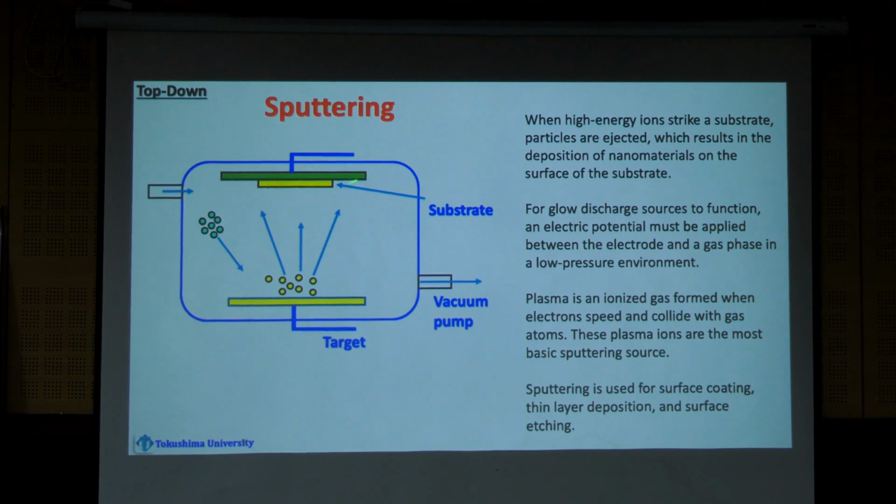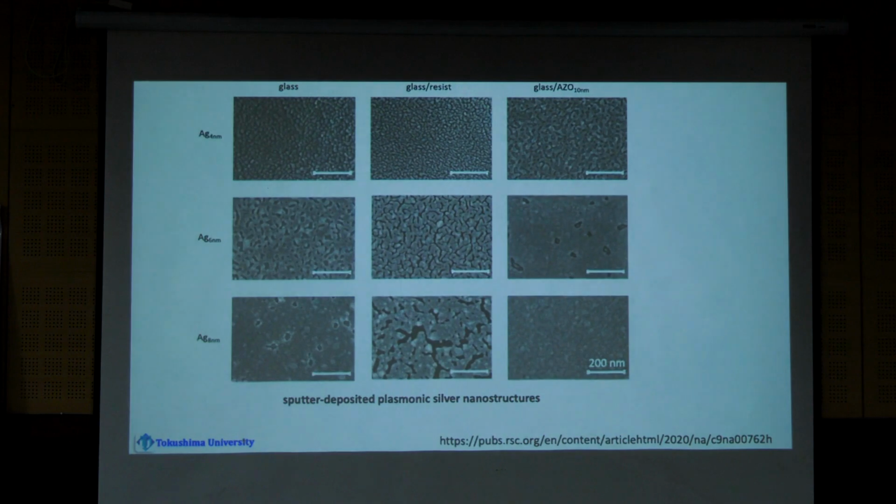Sputtering can give you uniform deposition. Also, sputtering is used for low nanometer scale. Like if you want a 1 nanometer coating, then sputtering is very good. A 2 nanometer coating of certain material, Ag, Au, you can use sputtering, and uniform deposition. Look at this, okay? These are examples like Ag, okay? 1 nanometer, okay? 6 nanometer, 8 nanometer. So 1 nanometer is uniformly deposited.